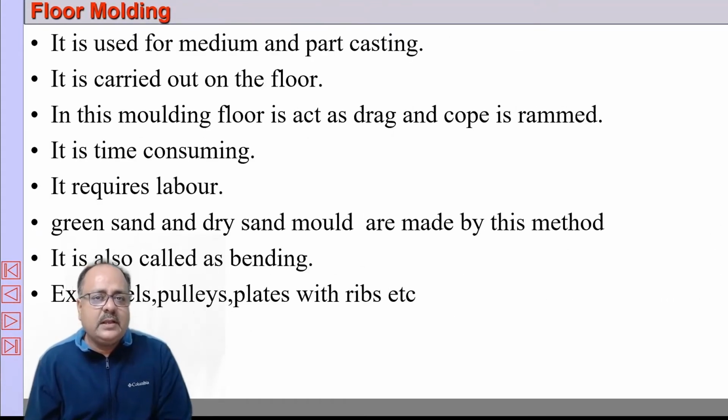So floor molding, as I have said, is used for medium size casting. It is carried out on the floor. In this molding, the floor acts as a drag, and the ramming is carried out in the floor itself, and it is time consuming. It requires labor and is mainly used for green sand and dry sand molding.